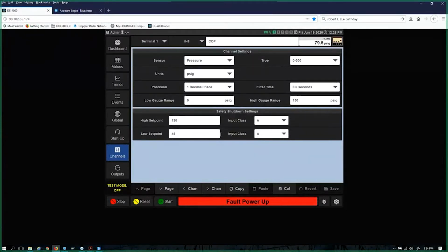No matter what we do, despite our best intent on startup situations, there are always certain times where somebody says, it's really cold and my unit's going to take a lot longer to warm up. Maybe I have all my process pressure channels set up as Class C's for my low process pressure kills, but they're all set at 600 seconds, 10 minutes. But let's say I had a unit that I can't load, and therefore I can't get those channels off their low kill points before that 10 minutes because the system's very, very cold.